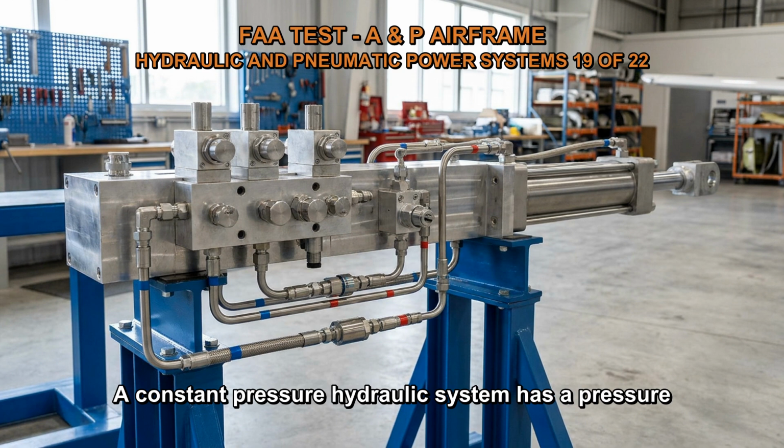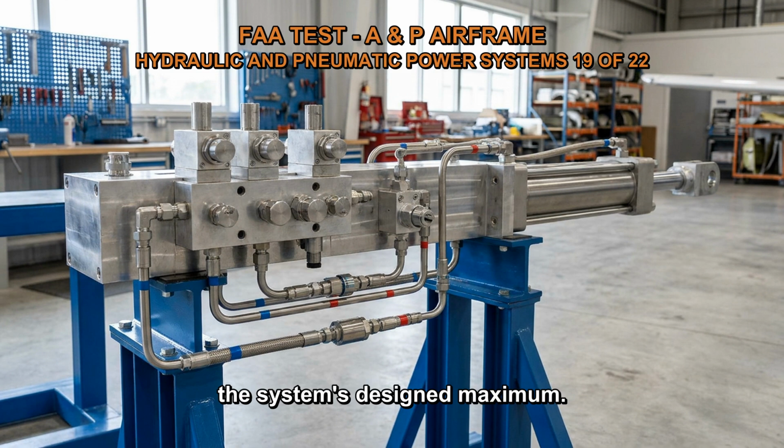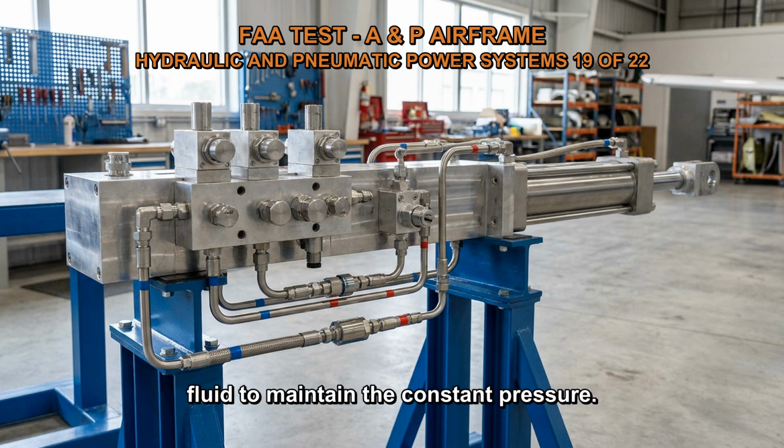A constant pressure hydraulic system has a pressure relief valve which opens when the pressure exceeds the system's design maximum. If fluid is added while the system is pressurized, the relief valve will open and release fluid to maintain the constant pressure. Once the system pressure is reduced, the fluid level will increase in the reservoir.